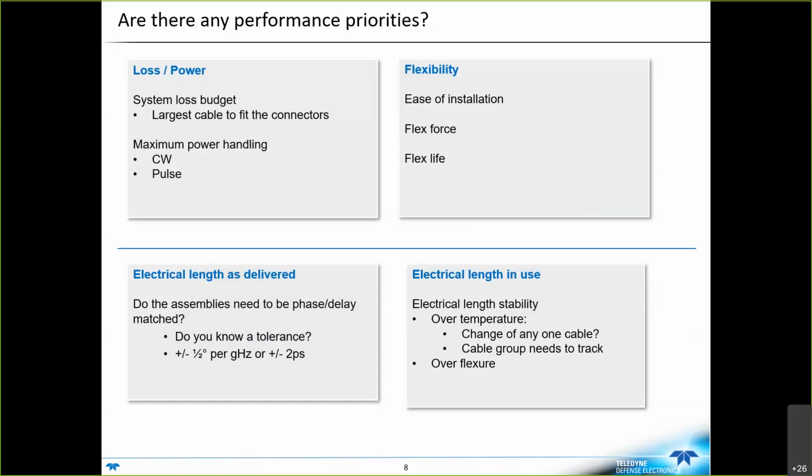It is a larger cable, like in our FlexCore series, where you're concerned about something that has low flex force. Ideally, a cable is part of a system that's moving. Maybe there's a gimbal mount that's motorized and things are moving and we can't load the motor down too much. So I'm very concerned about what type of flex force, which actually gets expressed as Tabor units in some of our documentation, how well is that going to be?